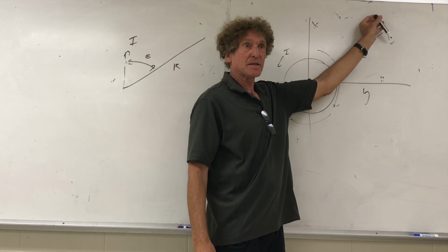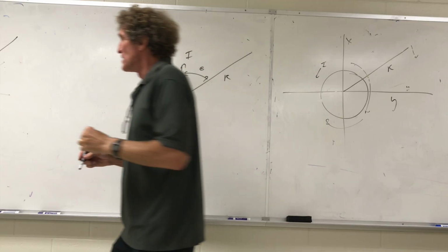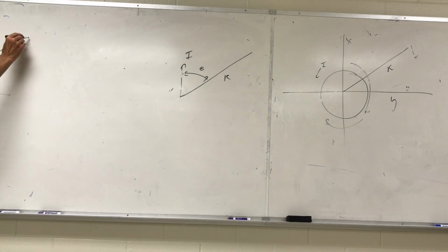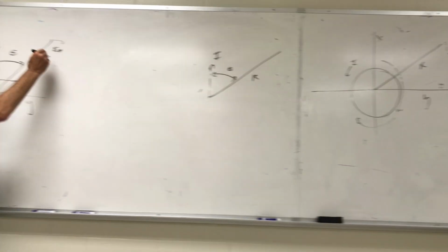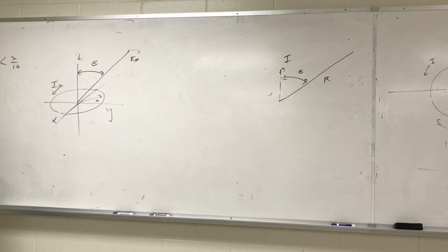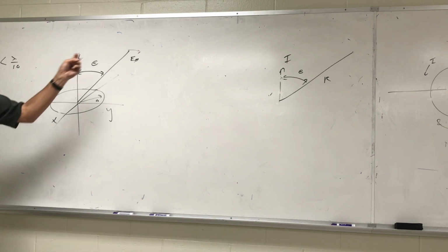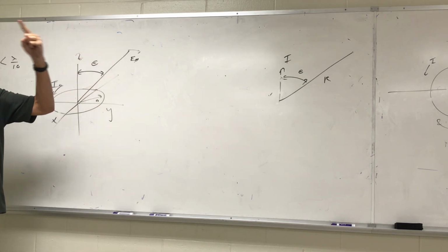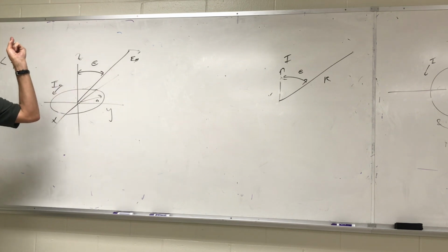But this isn't the far field. The E field will always be in that plane. So if you look at this loop, what does it mean out here? It means the electric field itself would be in the phi direction. Can you all follow me on that? It wouldn't be in the theta direction, it'd be in phi. It'd be parallel to the xy plane and circulating this way. Do y'all follow me?